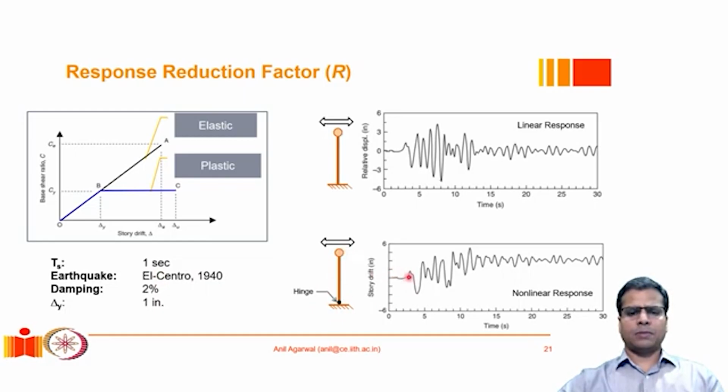and again the displacement at the top is measured. So one thing we can obviously see is that in the linear system we were getting a net zero displacement at the end, because the system was coming back to zero position after the earthquake loading was completed. In a plastic system, however, there is a residual displacement. After the earthquake history has completed, there is a leftover displacement in the system, which is expected because the system has a plastic deformation, which is a permanent deformation.